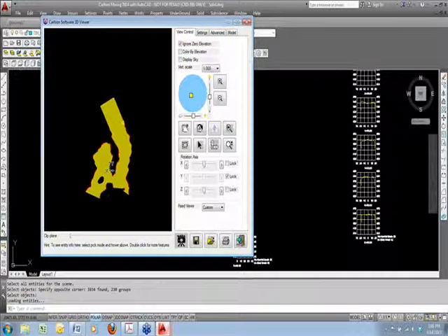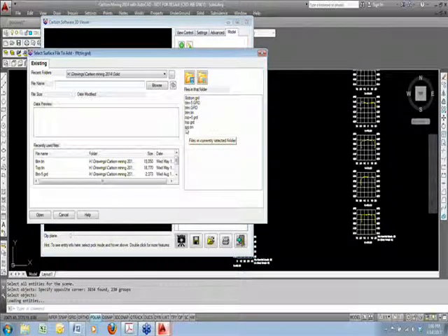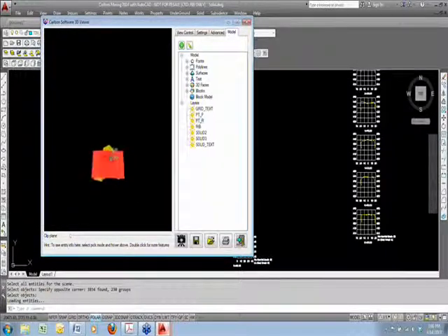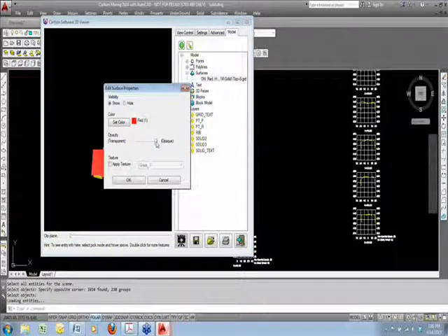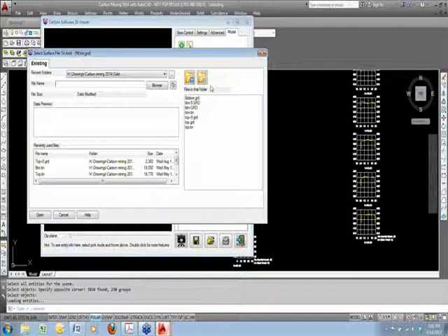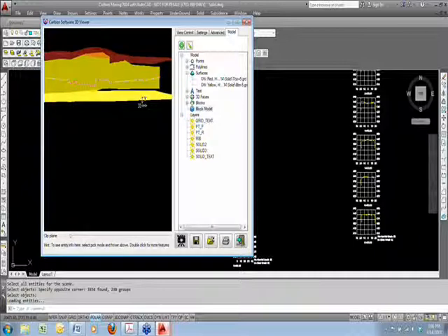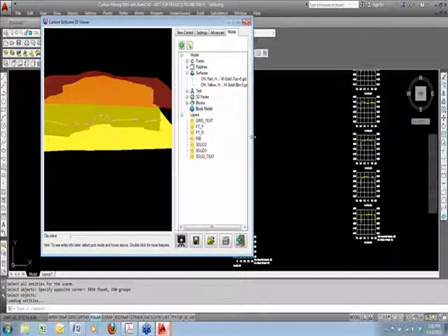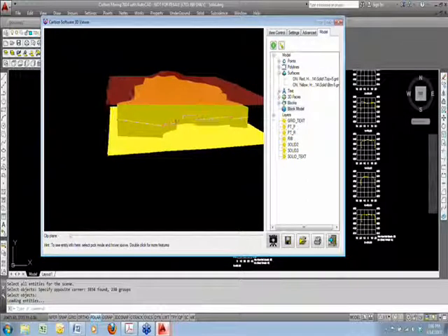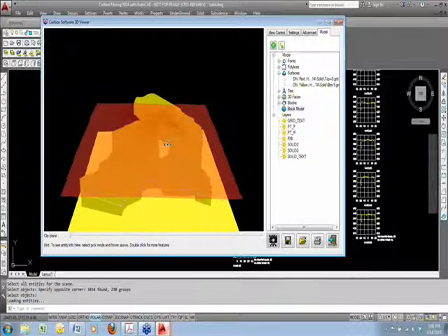And then the reason I just reported out only one strata was because if I bring in my surfaces, add a surface, I had in my pre-calculated model, I had top +5. Let's make that transparent so we can see the solid behind it. And then I'll add the next surface, which is just a bottom. Bottom I did -5. So that was what defined the rock zone. And then if you had different seams that crisscrossed inside there, it would definitely break out the tons and volume by different material or seam name or grade. But the transparency is kind of nice, definitely for the solids and the ore body modeling.